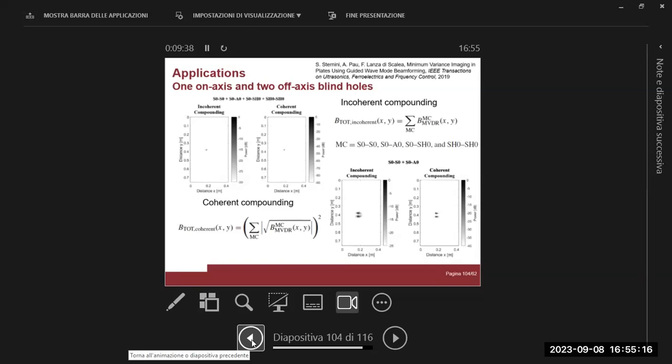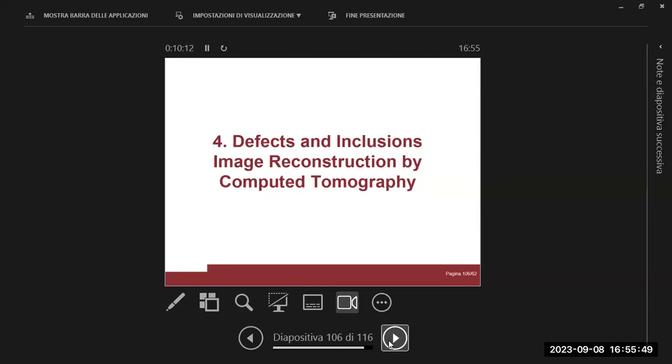For instance, in this case, we separated the contribution from the shear wave and from the pressure wave, and moreover, we applied some filters that are based on the physics of waves, meaning on the shape of the waves. That means that we projected the two components of the waves to pick up exactly the part which contributed to the response recorded by the transducers.